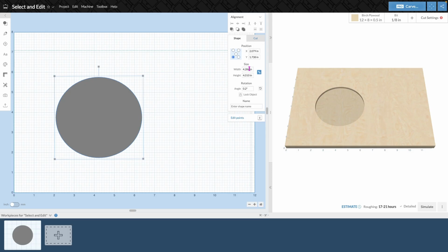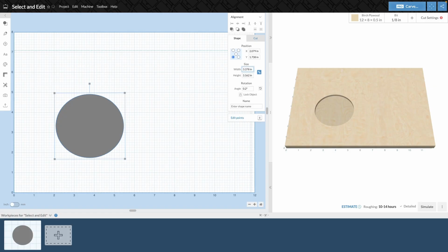Another thing to notice is that when you select into the size box, you can type more complex measurements into the system. So I can do, say, 2 inches plus 35 millimeters and press enter, and that will change that dimension in the width and the size box depending on what that measurement ends up being in inches, which is what my easel is set to.